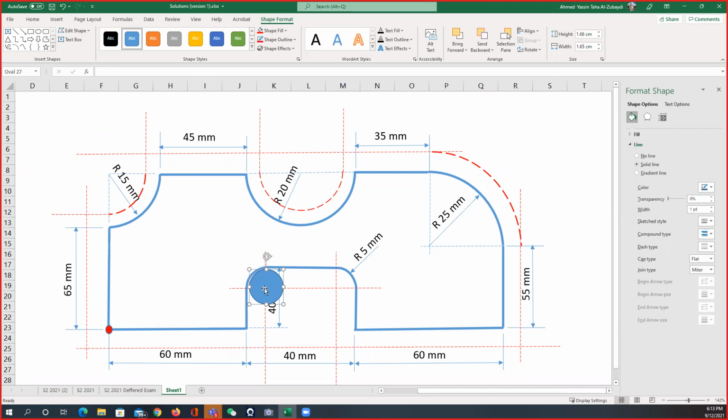In the milling operation, it's impossible to make an inner corner to have 90 degrees. It's impossible. Why? Why is it impossible to make an internal corner to have a sharp 90 degrees? Exactly, because the cutting tool is rounded. So definitely the location is going to be rounded.